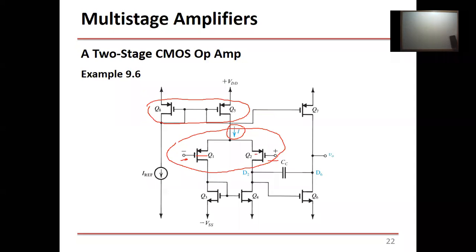Again, this is a current mirror, right? This is another current mirror. Why? Because you have a good current here, and you'd like to replicate it in these two branches. So this is actually an active load. Instead of having RS here and RS here, which resemble RD and RD in the NMOS, we designed them because we don't want to see any resistors here. So instead of having a resistor here or a resistor here to bias these transistors, we bias them using this current mirror. Okay, so it's an active loaded differential pair.